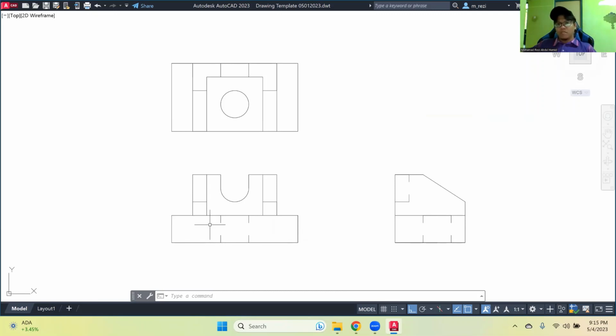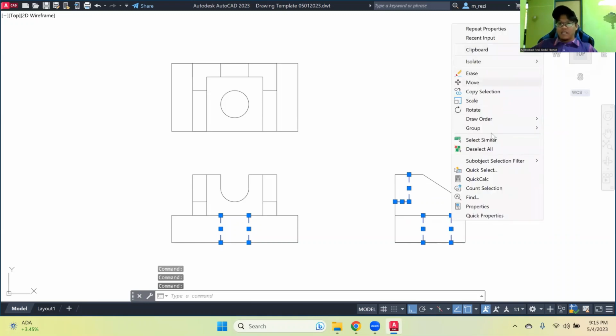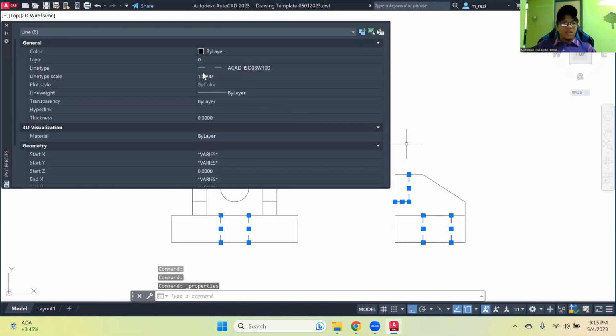as you can see, they are too far away, I would say. It's not the line, the dash of that particular line is too less. So what you can do is you can always adjust, click here, here, and then here, and then here, and then you can adjust the density of the lines. Go to properties, line type scale, you can reduce it so that you have more dash.